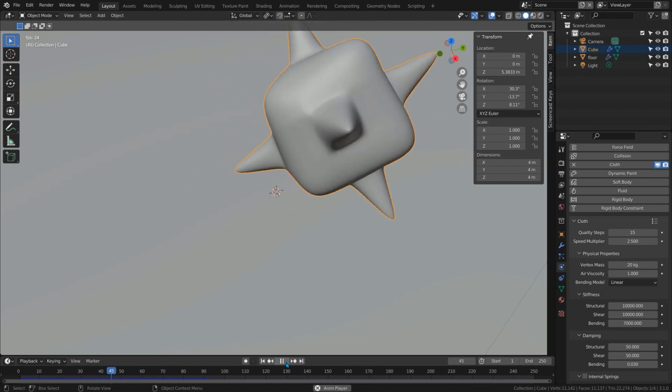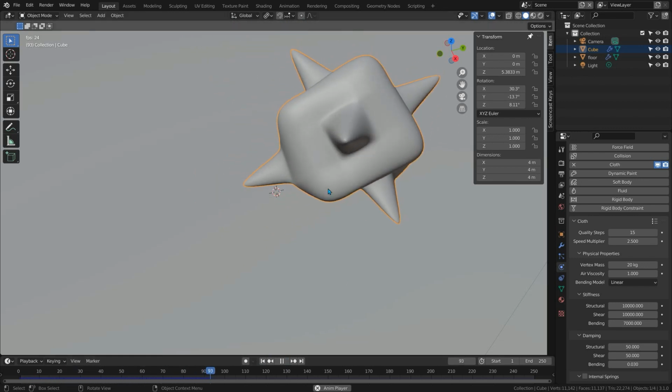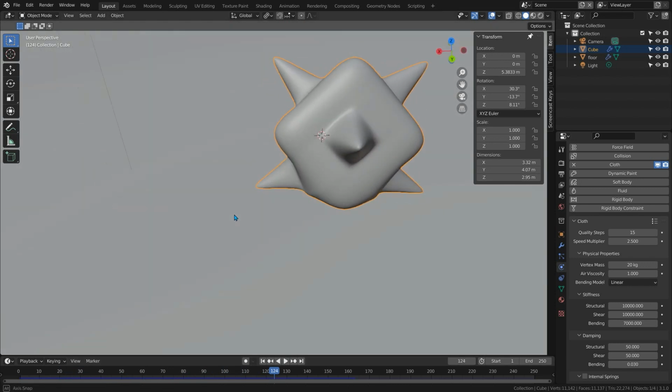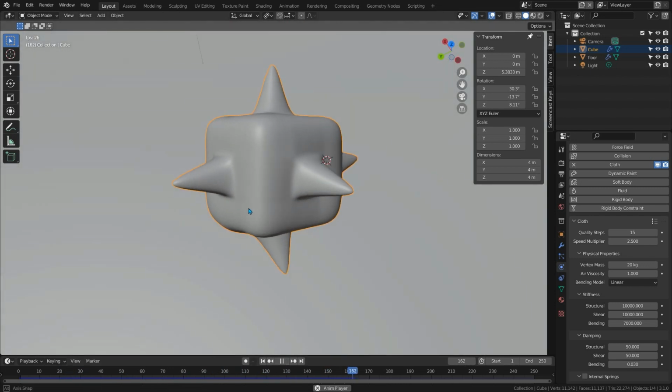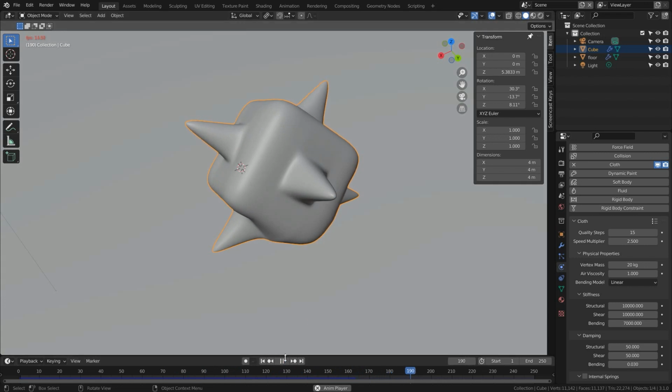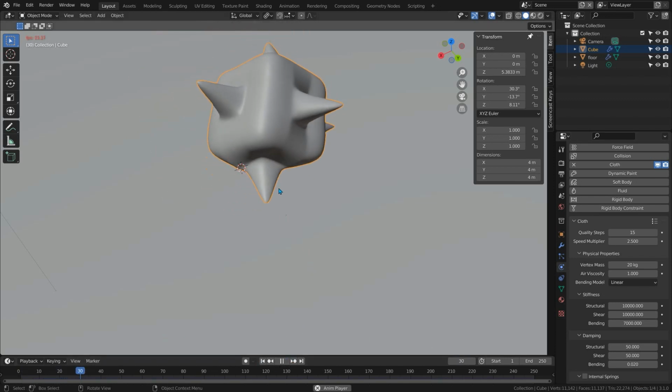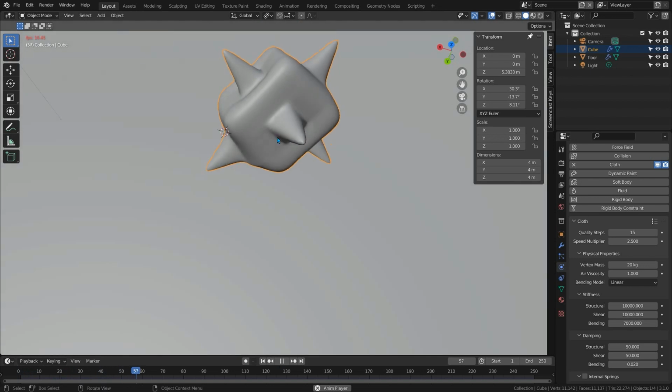Wherever we had the tightening loops, we can now see them as ridges around our shape, and that's going to be a real problem in soft body simulation or any deformation of this kind of mesh. They really are quite obvious. In fact, let's set the bending even lower. Let's go to 0.02 and take a look at that. As it simulates, you can clearly see all of these ridges all around our mesh. It's just not good enough. Those edges are changing the actual structure of our shape, and that's what we need to avoid, certainly in soft body simulation.